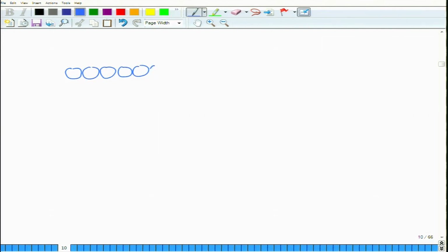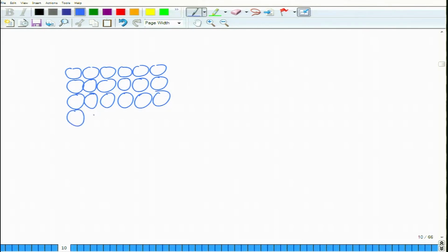material. So you have a structure like this, which is a perfect structure, okay. Now what we do here is we remove some of the atoms. So we remove these two atoms, let us say. So what happens in this case now, this structure will slightly distort, because you have created an extra row of atoms in between which does not completely go through the material.